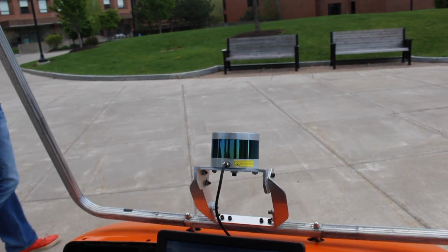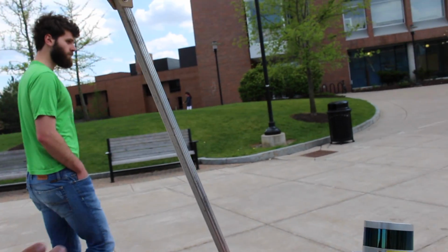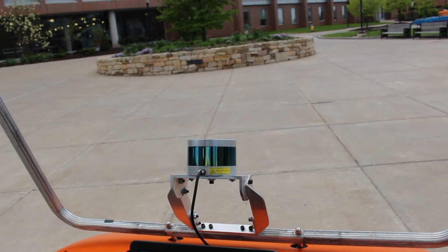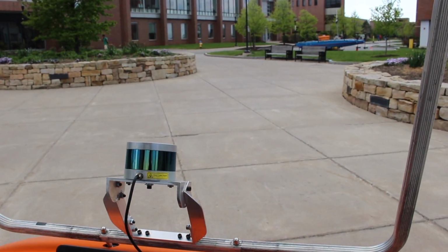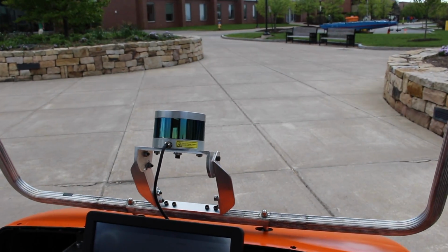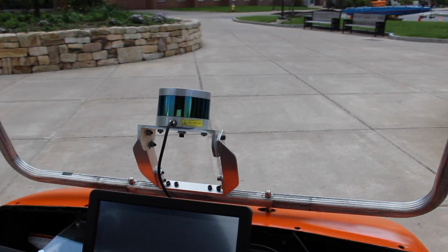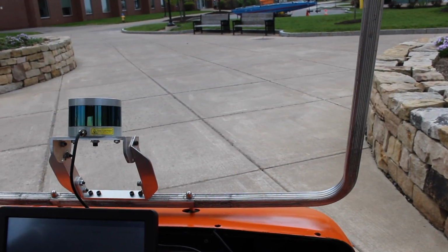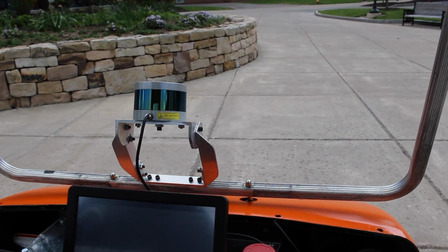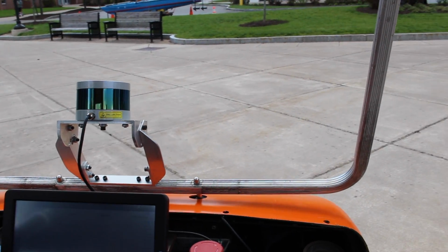A way to get it back on path is to actually have a moving obstacle in the way and push it in the direction that you want to go, although of course this is not ideal. What we recommend is to absolutely get better odometry and localization working, and that would include using a much better IMU. If the cart has a good path to follow, it actually behaves very well.